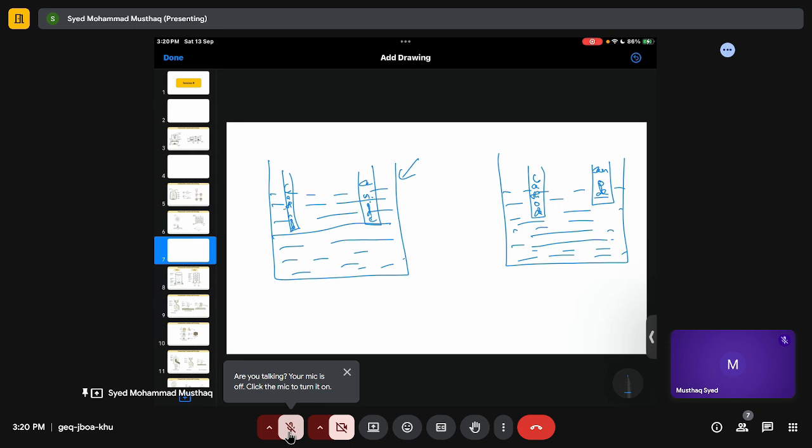So for example, this is 99.9999% pure copper, and this guy is 95% pure copper, right? So what we are trying to do is take charge from here. If it is positive here and you give negative there, we are taking charge out. That means the copper will dissolve into the solution, travel through it, and get deposited onto the cathode. That's how you create pure copper in copper industries.